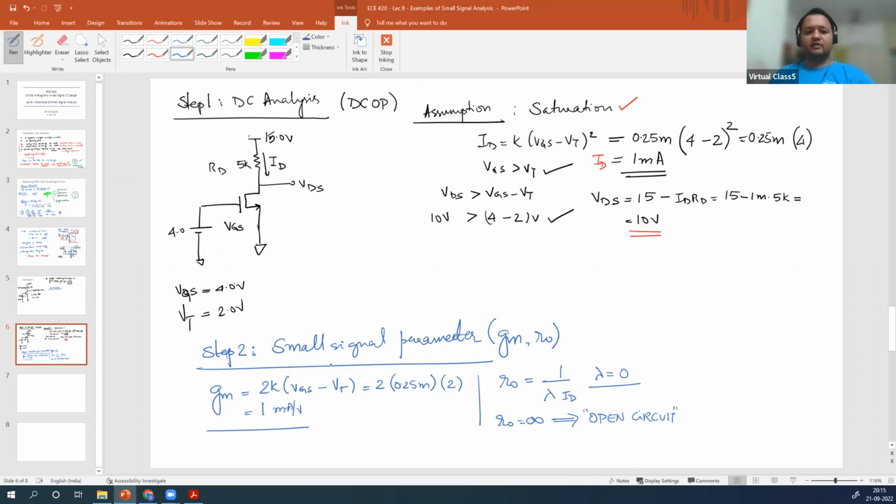You have identified. Now, what does that mean? How does your small signal equivalent look like now? Let us draw the gray box. Always remember, draw the gray box when you are working in the beginning. D, G, S. Next step, VGS.